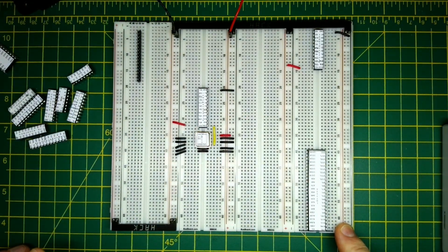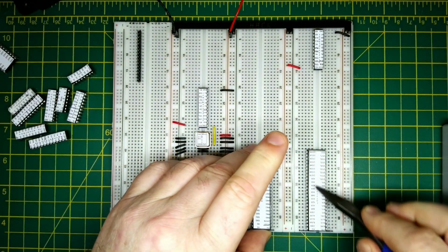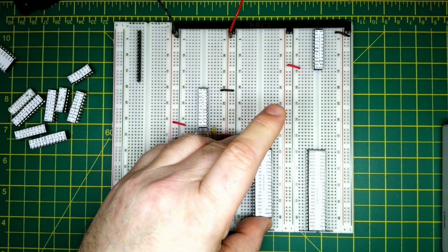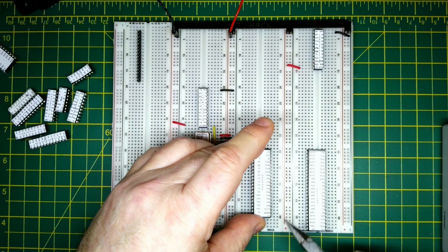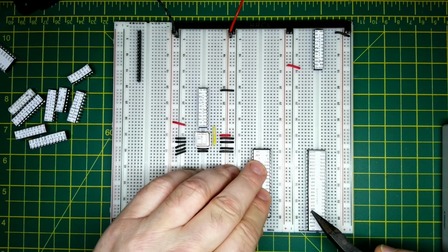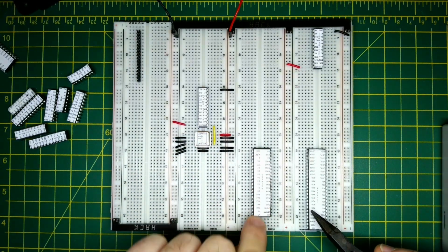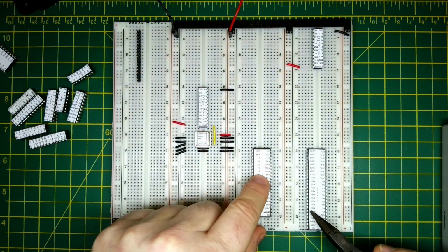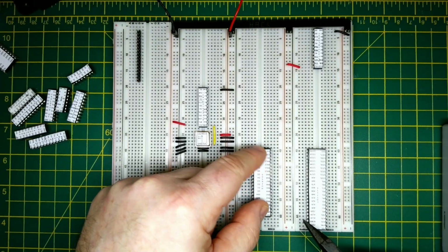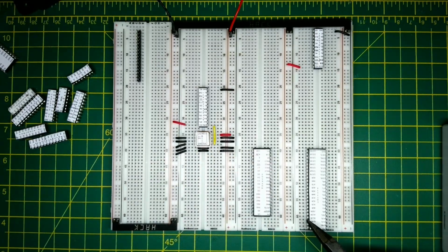Then the CRTC, a lot of the address lines here are going to be wired up to here. Again, for the CRTC, we need to make sure that the A1 line is lined up with the MA0 line. And again, we probably want to have more space on the left-hand side because most of these are just going to be wired straight across here. Can plug that in there.